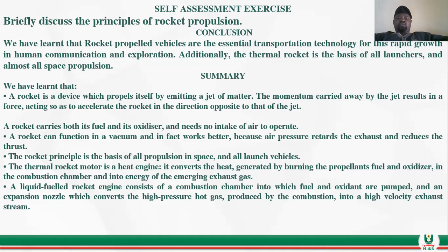A liquid fuel rocket engine consists of a combustion chamber into which fuel and oxidant are pumped, and an expansion nozzle which converts the high pressure hot gas produced by the combustion into a high velocity exhaust stream. That is exactly what we are looking at today, and I believe you have learned something about rockets.